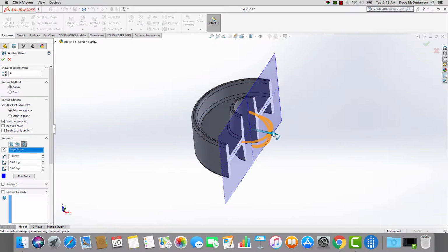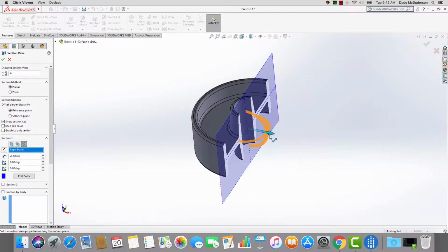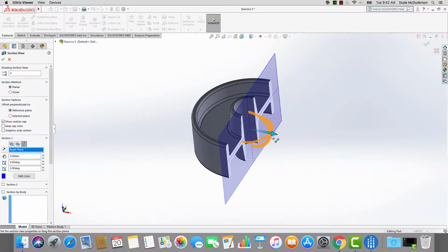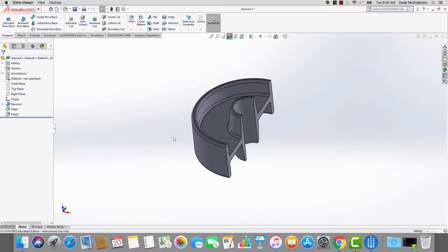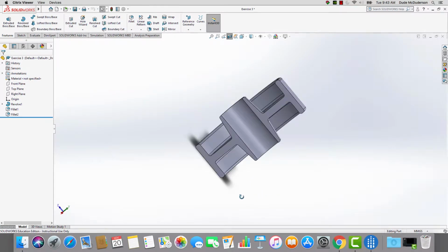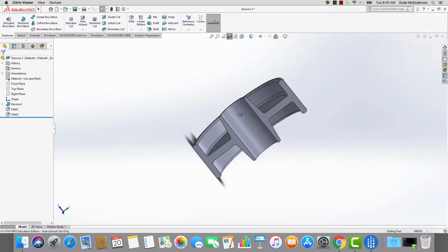At this point you can actually change where you're looking at in that section. We want to look right to the center of our object, and we can then take a look at that section view. So if we select that section view, you'll see now what we're seeing, the center of that wheel. If we look at this, you'll see that the geometry is mirrored about this central corridor, the central axis here, the hub of the wheel. And what we're looking at is geometry that looks pretty similar to what an I-beam might look like. And that's the thing we're actually going to sketch.